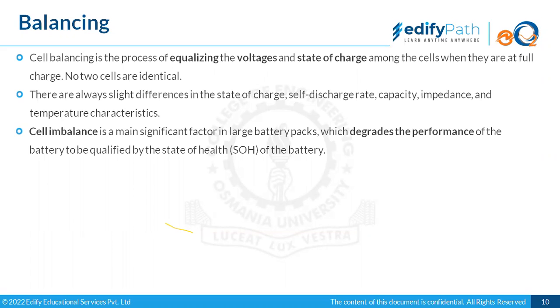The same is the case with discharging. Say we have utilized this battery and gone 60 kilometers, and now it is fully discharged, the vehicle has stopped and is not allowing the vehicle to move further. If we check the voltage across every cell of the battery and it shows equal voltage across every cell, we will call it a balanced battery, because it is discharging and charging at the same rate and every cell is contributing. Every cell is uniformly discharging and uniformly charging. That battery we will call a balanced battery.